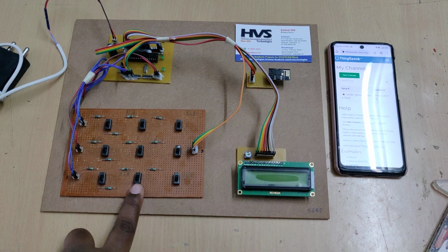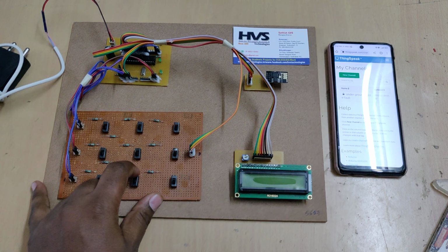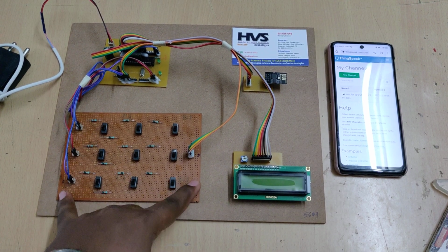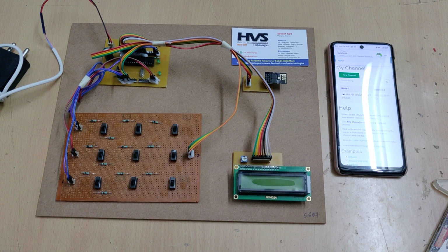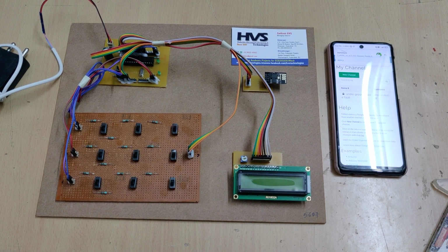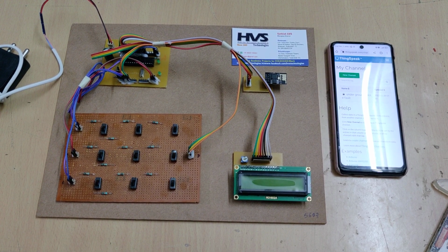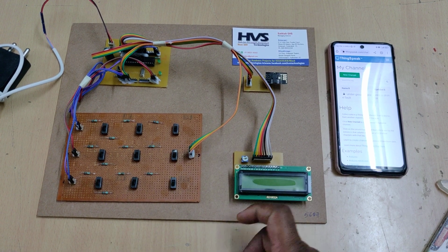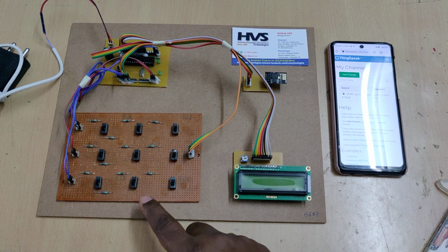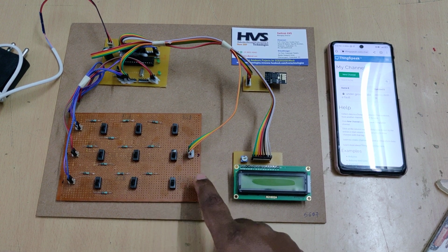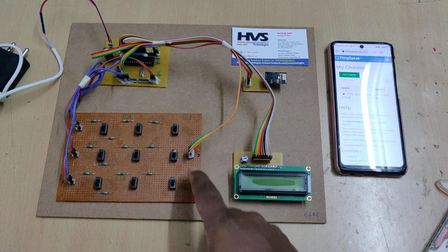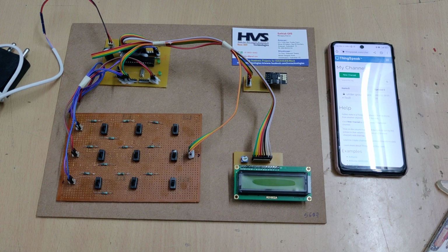Now here, the sensor circuit output is interfaced at the A0, A1, A2 pins, as these are the analog input pins of the microcontroller, so that we can measure the analog voltage. The voltage drop occurs in the range of 0 to 5 volts, so we need to interface that variable drop voltage to the microcontroller A0, A1, A2 pins.